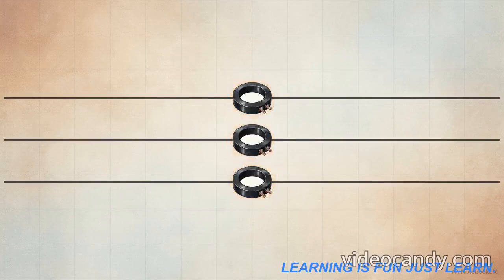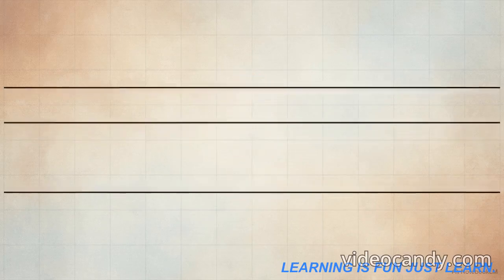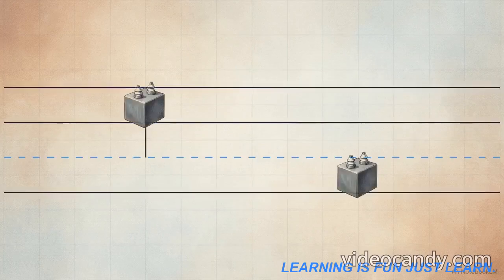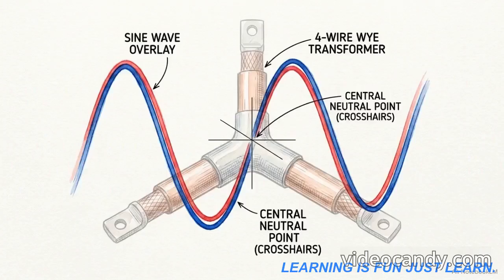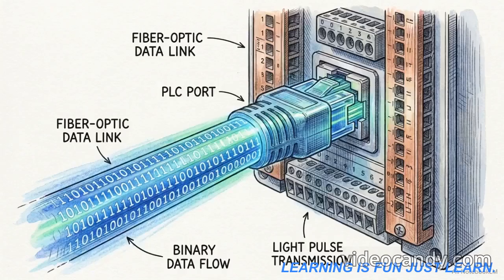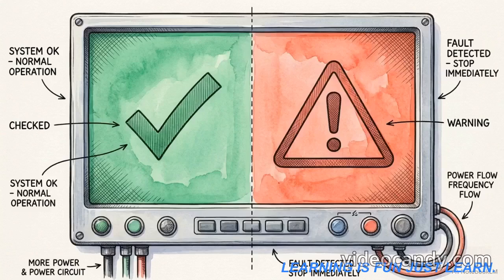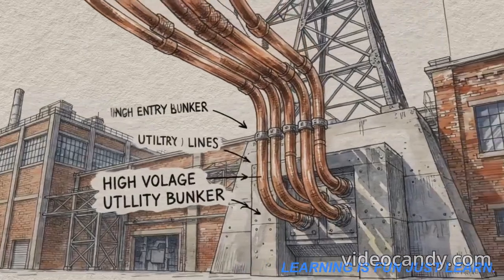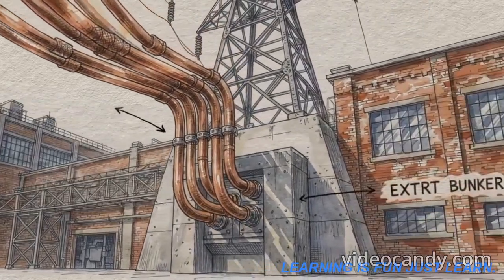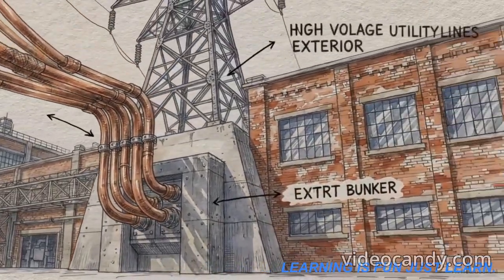Extracting electrical values requires specific geometric arrays. One method is the three-wire open delta, using exactly 3 current transformers to monitor phases. Alternatively, a 4-wire YE configuration removes the current transformers, tying 2 potential transformers to a central neutral line. This specific 4-wire YE setup with 2 PTs is mathematically required if you need to accurately capture line-to-neutral voltage readings. The physical metering topology dictates the exact data fed back to the logic controller, determining whether the drive registers a balanced grid or a critical line fault.